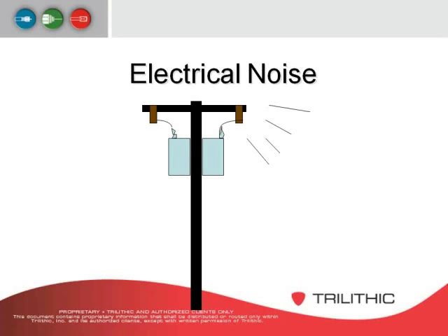There are also things called taggers, and taggers will also aid you in not being fooled by something that appears to be a leak but is not. Trilithic has the CT2 and the CT3. Those are both channel taggers. The CT2 works directly off of the head-end equipment, the modulator. With the CT3, if you do not have a modulator or a particular channel at that location, then you could use a CT3 and it generates that RF carrier.